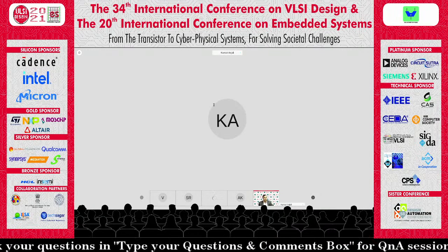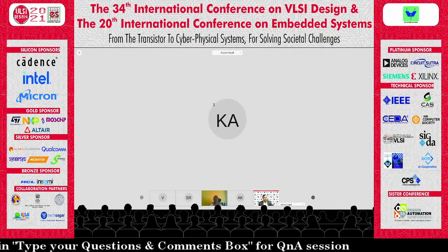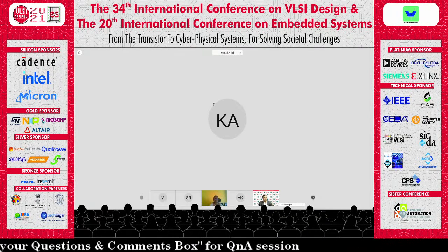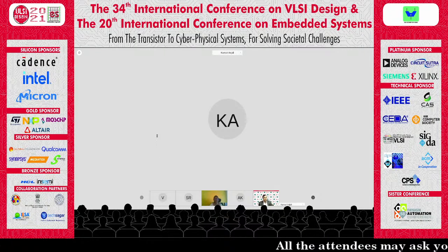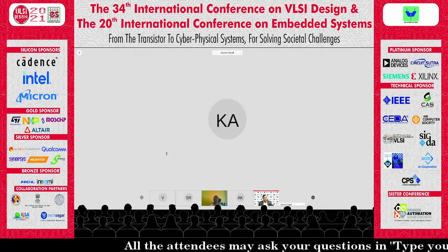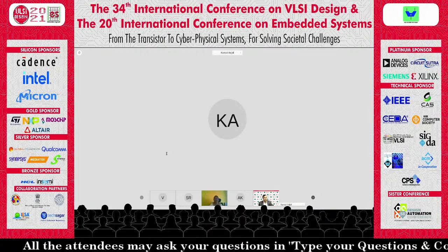So, what we did is, at every possible location in the address decoder which we made where we can get address decoder faults, we have injected resistance values, and we verified that. But for the PPT we included only a few faults that we can show here. At every possible location and with different resistance values, we are trying to check whether it covers or not. Accordingly, this algorithm is defined.